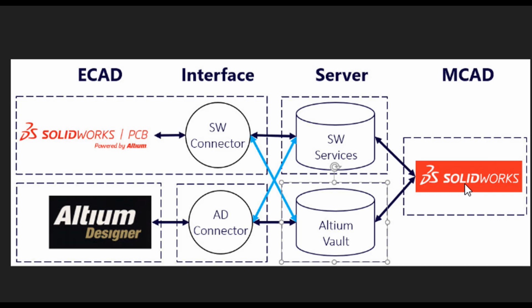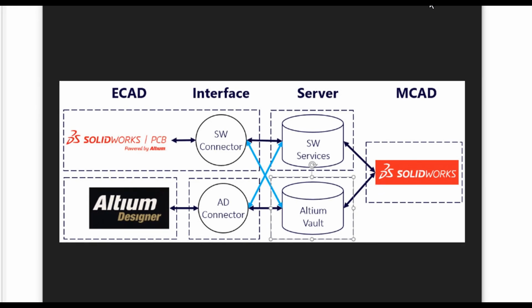And again, just to remind you, this will work best if all of the connector services and CAD programs are of the same version. And in this case, we will be using Altium Designer 18. The connector was designed for 18, or at least this version of it. We're using SolidWorks Services, which was for version 2018, and for SolidWorks CAD 2018 as well. So with that, let's get started here.